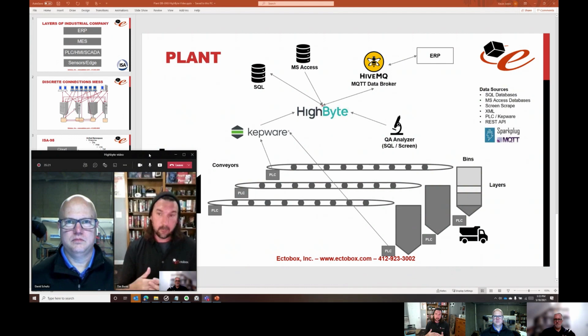Well, how does he know what quality he's going to put in? He looks at the bins and he looks at the quality that we've computed in each of the layers to know, oh man, everything at the bottom of bin 3 is like 4% moisture. We definitely can't use that bin. Looks at bin 1 and it's less than 1%. That's amazing quality product. But bin 2 is the Goldilocks. It's right there. It's 1.5% moisture. That's the most we can use, but still meet the customer's threshold to have less than 2% moisture in their product.